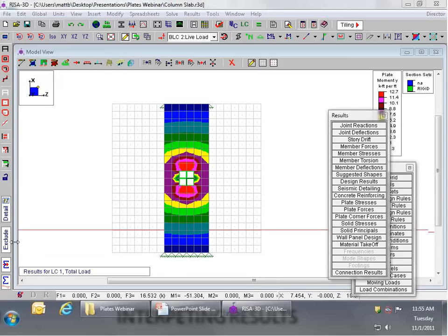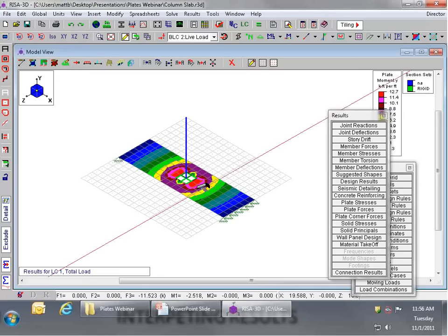Now, it is important when you use this internal force summation tool that you're in a plan view or an elevation view. And the reason is that we report these values relative to the direction you're looking at the model in. So if I snap to an isometric view, note now I have M1, M2, and M3. Because what we're doing is we're showing you the moment relative to a vector sticking out of my screen, not relative to the model in any way.